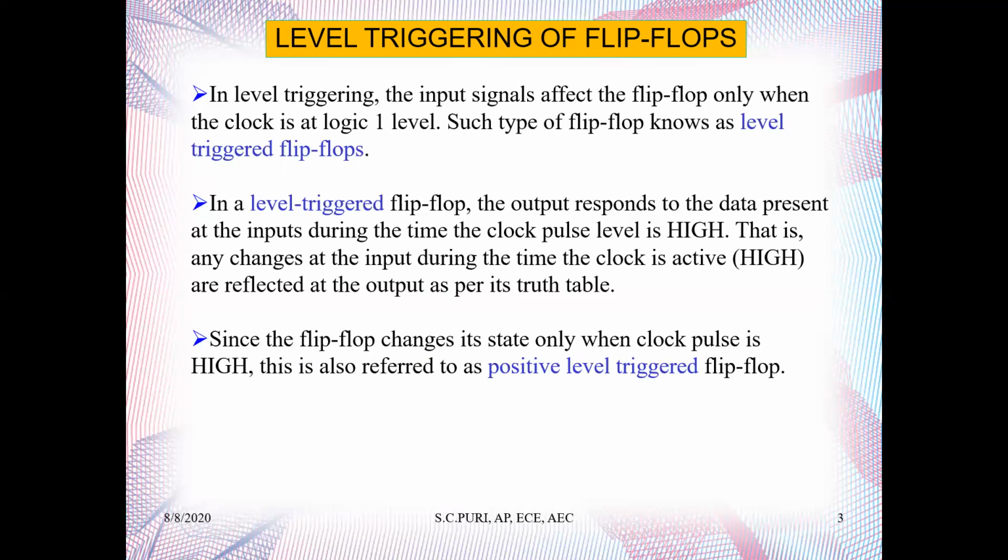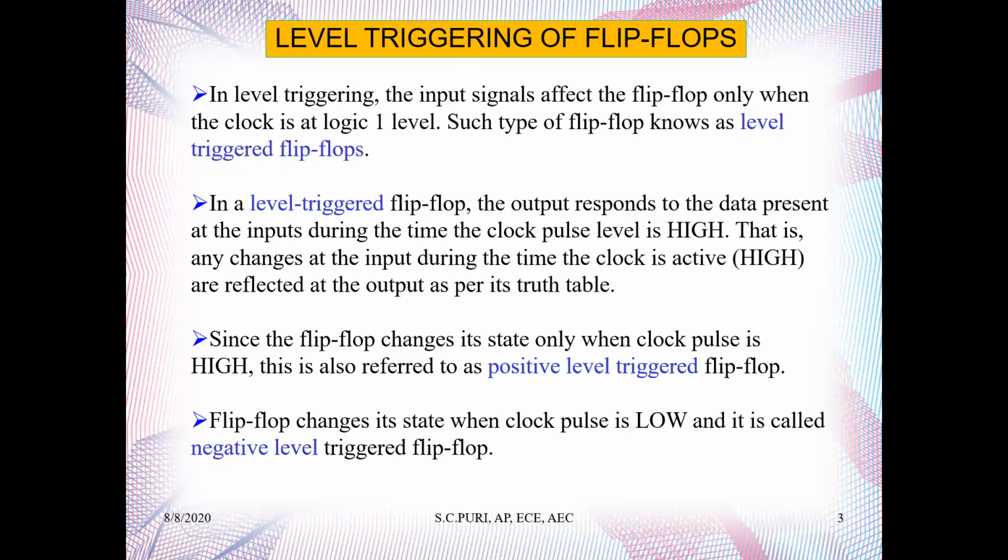Since the flip-flop changes its state only when the clock pulse is high, this is also referred to as a positive level triggered flip-flop. Whereas a flip-flop in which the state is changed when the clock pulse is low is called a negative level triggered flip-flop.